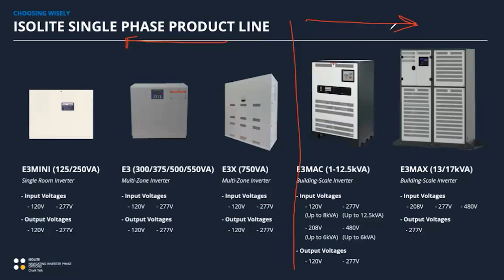Do I want this to be a 3-phase system so that I can rip power straight from the main breaker panel and then feed more sub panels downstream? Or do I need single phase because I'm going to directly power all of the lights and use my own circuit breakers as the protective devices downstream? So that's really where we start to make those elections all the way up there.